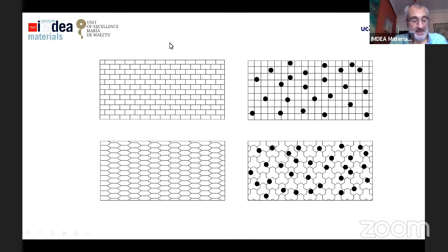And on the other side, in powder metallurgy, we see a porous material, because usually we have used a press and sintering process in which we cannot reach the full density. So we have a microstructure which is isotropic. We don't have a special texture like in forged materials, but we have these black points that represent the porosity.